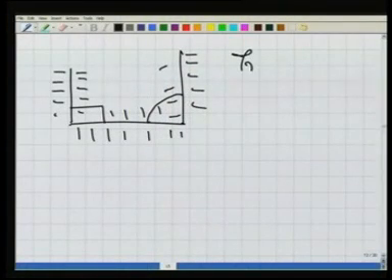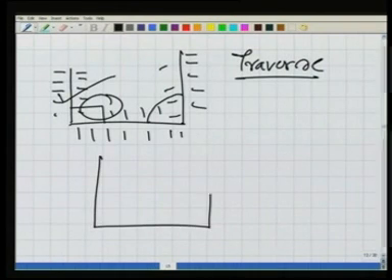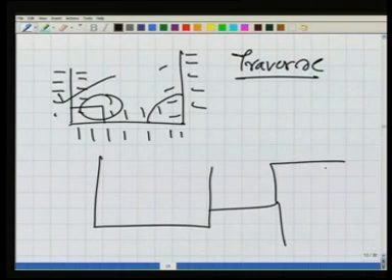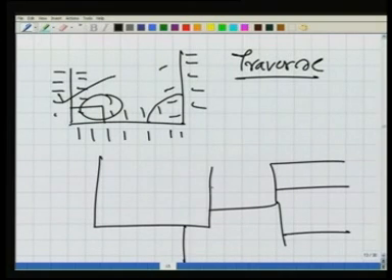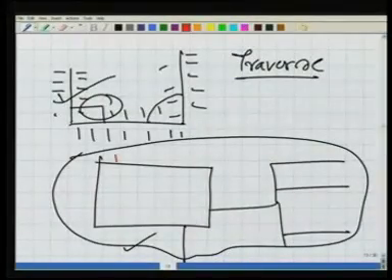So what we see here, one very important thing of the term which is called traverse. Because by measuring these lengths and these angles, we are able to relate or put them in relation to each other in our drawing sheet. So that may be a traverse here. So once this is the, and this we say the skeleton of the area. So again we are working from whole to part. The skeleton here is the traverse, and we are bringing this traverse on our drawing sheet, and then later on we are doing the plotting of the offsets.